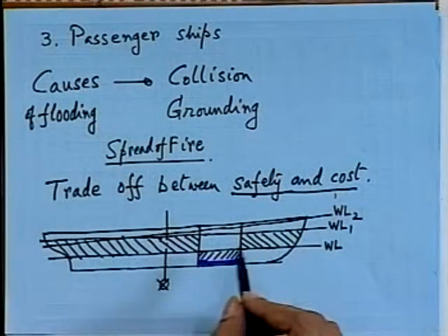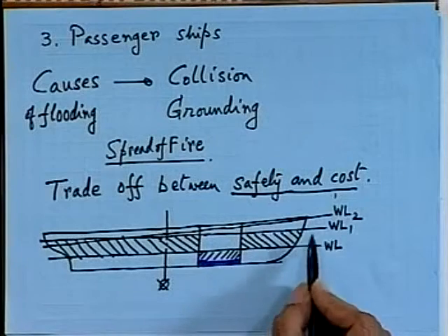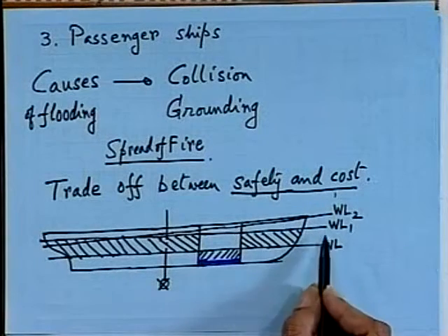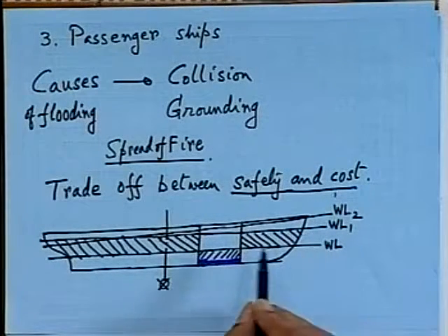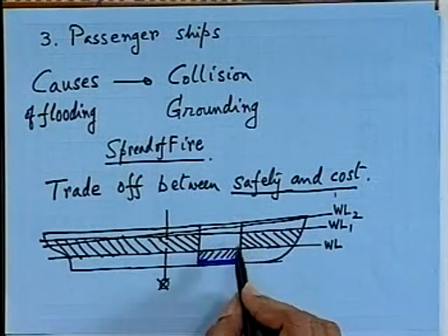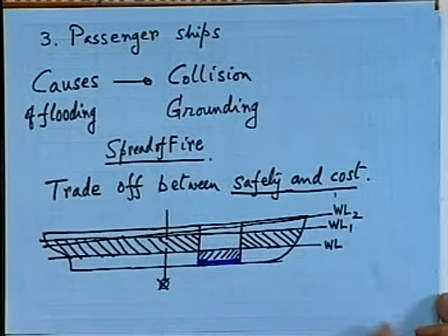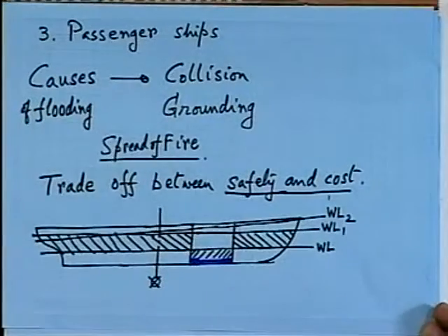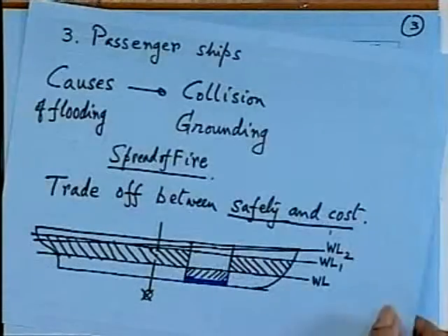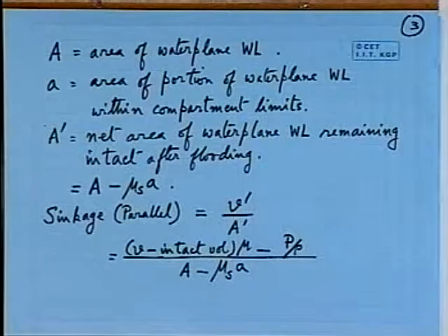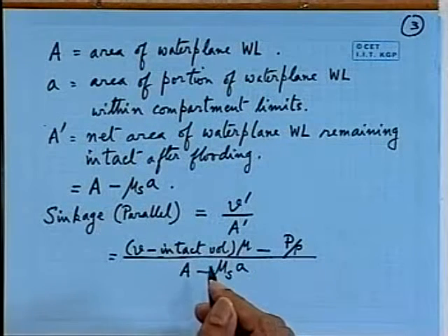Of course, for this layer of sinkage, it is not in meters. This can be quite small, but if you want to take the two damaged water plane portions of the water planes, then you can take an average.